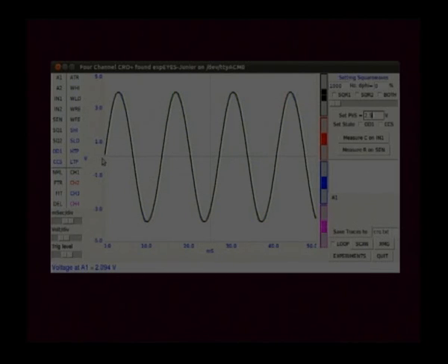Now, if you see how much time one cycle takes, if you click here it says around 13.3 milliseconds. But if you want to measure the frequency of this AC accurately, what you can do is move this CH1, you drag this to what is written here, fit.